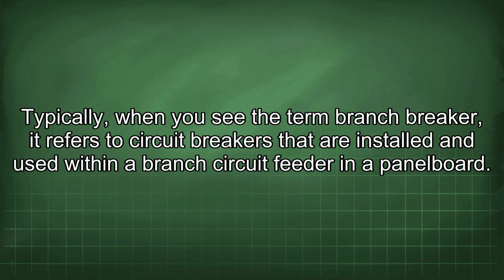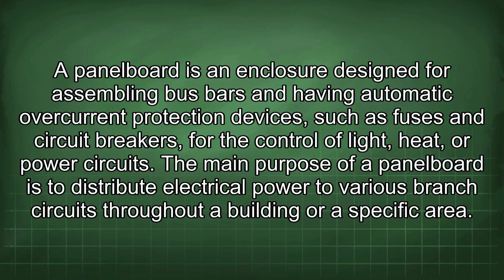Typically, when you see the term branch breaker, it refers to circuit breakers that are installed and used within a branch circuit feeder in a panel board. A panel board is an enclosure designed for assembling bus bars and having automatic overcurrent protection devices, such as fuses and circuit breakers, for the control of light, heat, or power circuits.